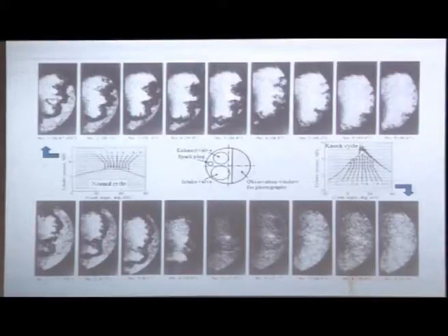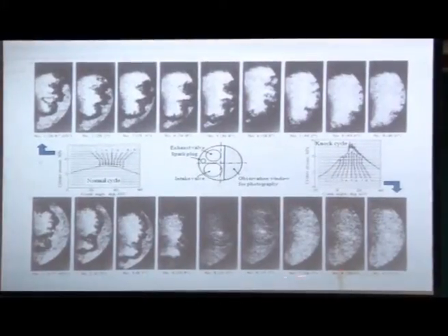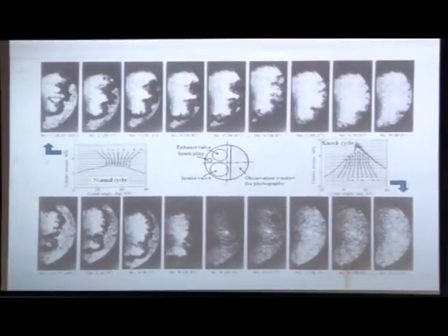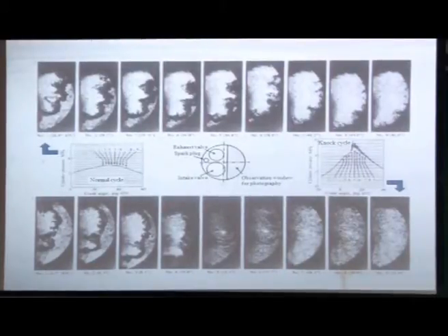So this explains how the knocking can happen and how you detect that knocking. Everybody will have no access to such an engine, but a pressure crank-angle diagram, anybody and everybody can do with little sophistication. So with very, very small instrumentation, you can figure out just by looking at pressure crank-angle data whether your engine is knocking or not.